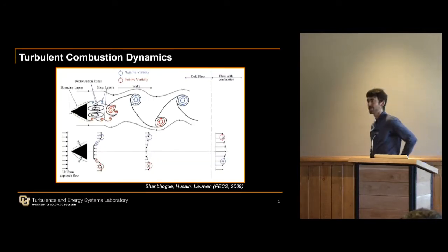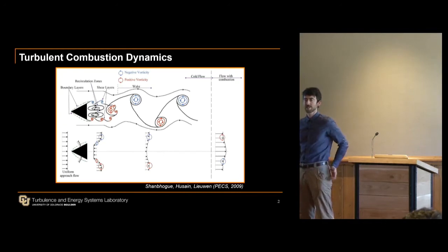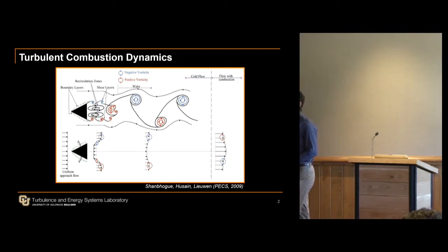So to delve a little bit more into the physics of these recirculation zones and how flames get trapped behind them, imagine, or envision, flow coming in from the left-hand side. So you have combustion reactants coming in from the left-hand side of the field here. You have a triangular prism, which is actually extending out of the plane in 3 dimensions here. And you have the flow then coming off the bluff body in shear layers and recirculating in the low pressure zone, just like in a stream with a rock behind it. It gets trapped here in the recirculation zone.